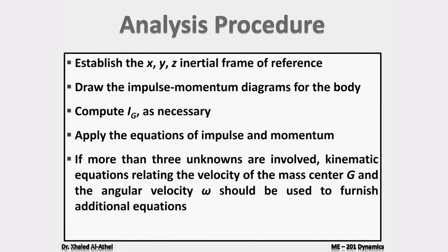Okay? So to solve the problem, the procedure is that first you have to establish the XYZ frame of reference or your coordinates. Draw the impulse momentum diagrams, which is similar to free body diagrams, showing the direction of all the forces acting on your object. Then you have to compute the mass moment of inertia as necessary. It could be IG, it could be IO, depending on what you need in that problem.